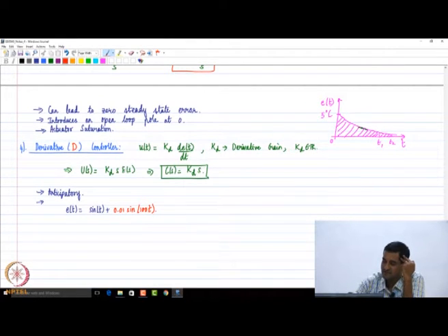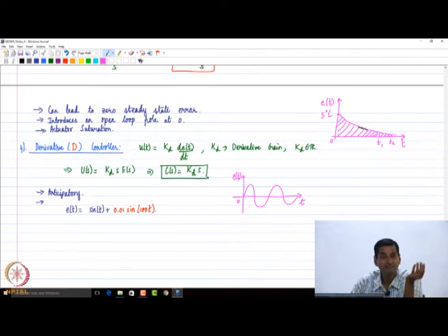So let's say I have an error signal, and this is just a notional example to convey the issues with derivative control. My error essentially oscillates as sin t. But what is sin 100t? It is high frequency noise.